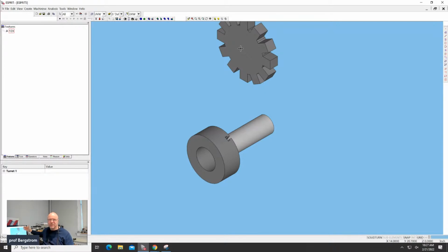It may be measured from 0 in ESPRIT, not from, you may have to subtract that -6 or -12 that we put in. Yeah, but when you enter a Z value in that menu, it shifts it. It shifts it the correct way, not the ESPRIT way. Yeah, it shifts it the way it is in the machine. There's a way to have the XYZ be correct, but I never bother. I know there's a way. I've never bothered to learn what it is.